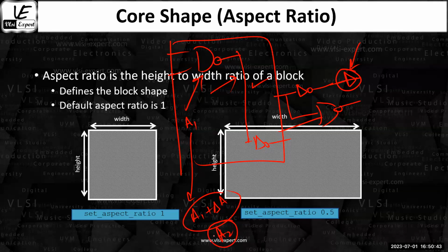Now, how are you going to place this extra buffer or make changes in the NAND gate if you have decided the wafer space based on the output of synthesis? Whatever calculation we have done, based on that you came up with a certain number. How are you going to make changes in your core area?